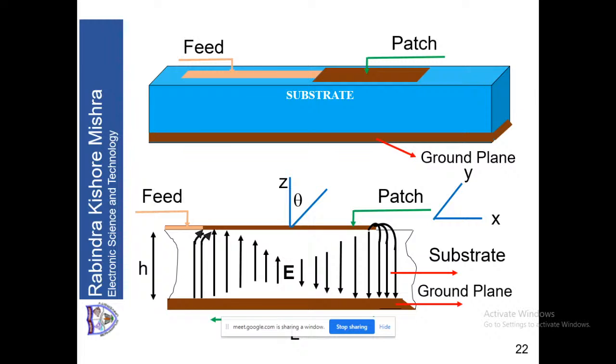Voltage is maximum at both the ends, but it will not remain a maximum throughout the patch. It will come down from the maxima, go to 0 at the center, then go to the minima. Therefore, the voltage maxima are of opposite phase. There is maxima, but they are of opposite phase.